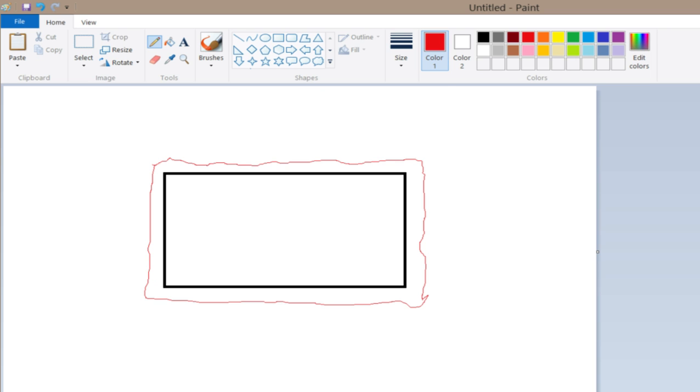Okay? So what I like to do is set my coordinate system somewhere in the upper left-hand corner. You can pick any corner you want, but what I like to do is use a small drill bit, anywhere between 0.010 of an inch and 1/8 of an inch, as a pointer, just as a pointer. And then I like to hover over the middle of this kind of goofy line. So I kind of hover over this point, and Professor Hodgkinson will probably show you this today. Hover somewhere over that point as good as I can see with this sharp point.